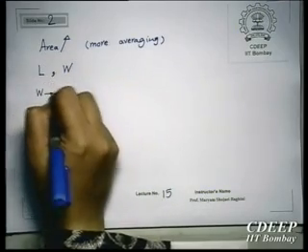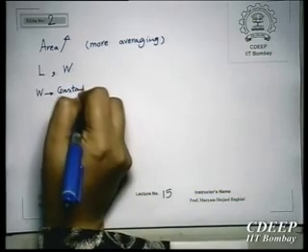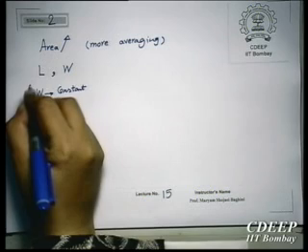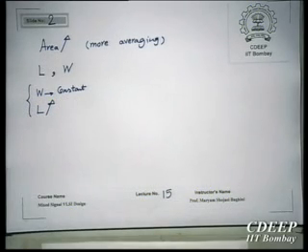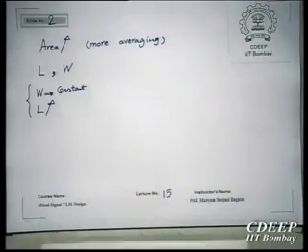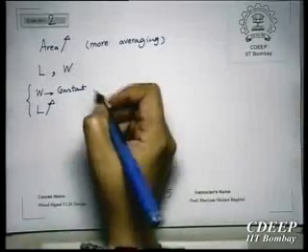Suppose W is constant and I increase L. How will this mismatch improve? First of all, when I say mismatch, it means that none of these transistors is actually a transistor with a length of exactly L. One can be L1, one can be L2. I have two transistors, so I focus on one transistor and see how increasing L will increase the number of samples. Therefore, the variation, in fact the standard deviation, will approach 0. Therefore, L will be L and nothing else.